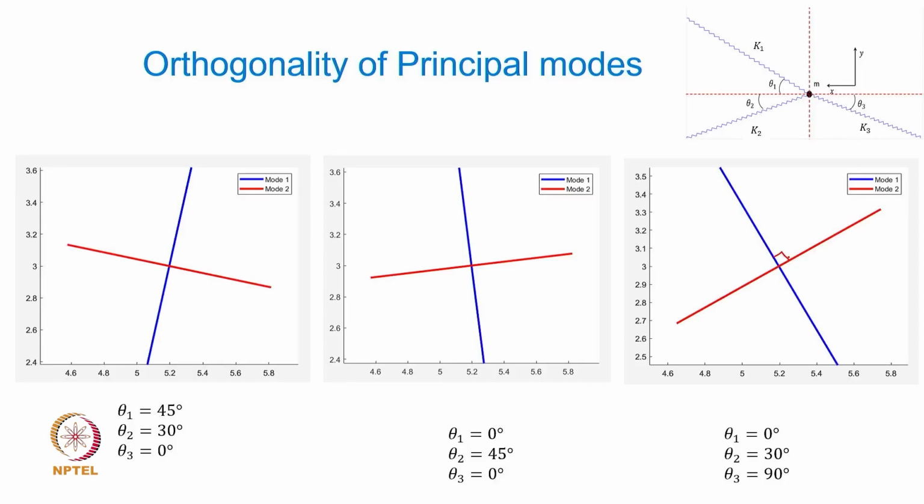So there is no shear stress, only maximum normal stresses in the 2 orthogonally oriented planes. Those are the principal planes, on which only the normal stresses exist.